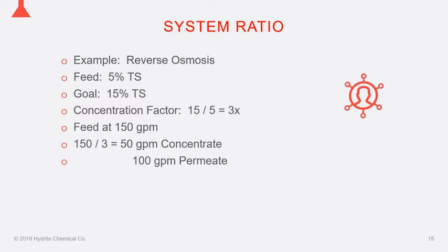So an OEM, original equipment manufacturer, such as Tetra Pak, such as GEA, CFR, MSS, Koalaris, the people we work with, MP&C, they would take that 100 gallons per minute permeate. They would know the temperature that we're running at, etc. And they would figure out how much membrane area it would take to create 100 gallons a minute of permeate. Once they have that number, then they have to calculate how many stages or loops to get the system to work efficiently.